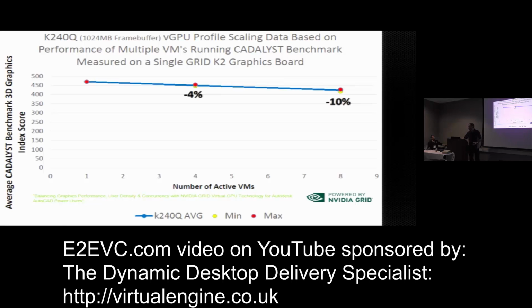And just a point there, your users are not going to be fully loading that GPU all the time. So this is the worst case scenario that you're going to see. This is 100% of the time AutoCAD running in a benchmark, spinning, doing its thing on those models. Your users are going to be looking up stuff, doing other things, going to get coffee. Not everybody's going to be logged in, so this is definitely the worst case.